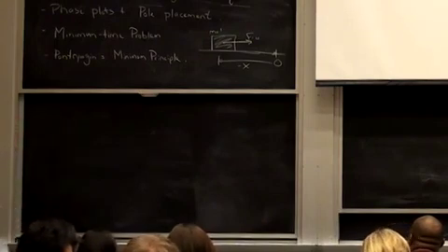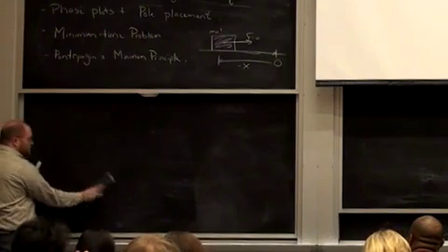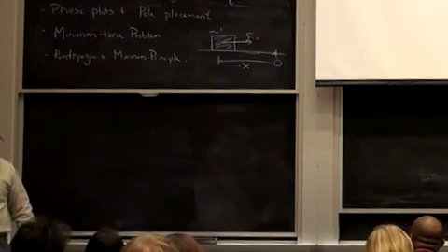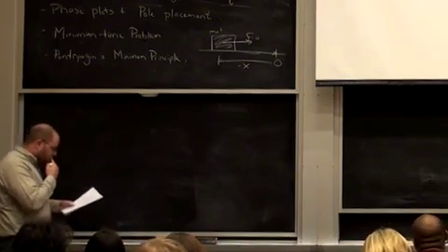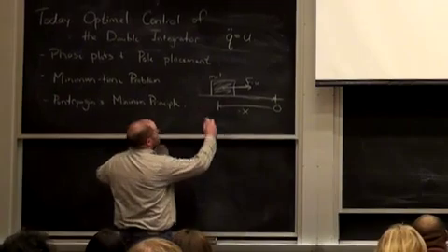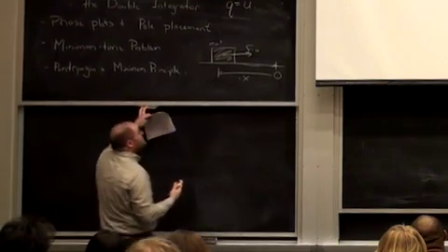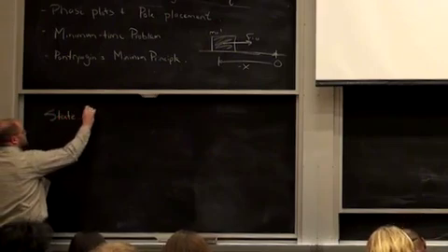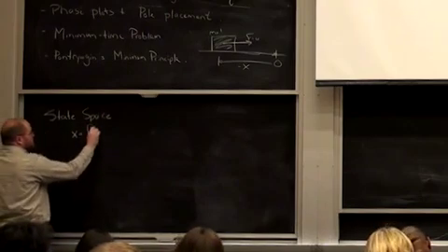Okay, so I've been trying to bring the tools from the different disciplines all together. So let me start by doing just a quick sort of pole placement analysis for those of you that don't think about poles and linear systems that much. So if I want to write a state space form of this equation, again, I've always tried to use q just to be my coordinates, and I'll use x to be a state vector. So a state space form of this is going to use the vector x to be, in this case, q and q dot.